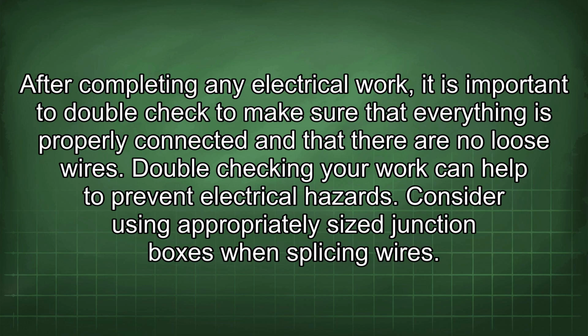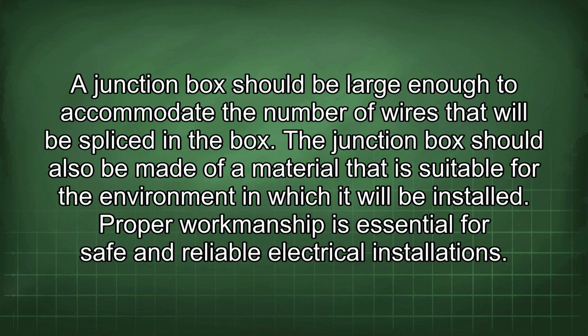Consider using appropriately sized junction boxes when splicing wires. A junction box should be large enough to accommodate the number of wires that will be spliced in the box. The junction box should also be made of a material that is suitable for the environment in which it will be installed. Proper workmanship is essential for safe and reliable electrical installations.